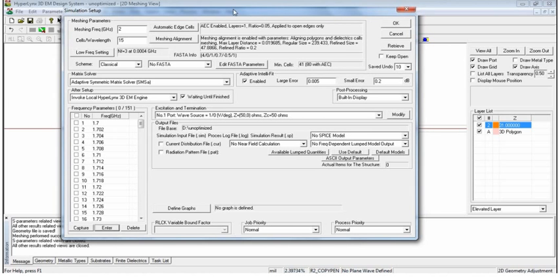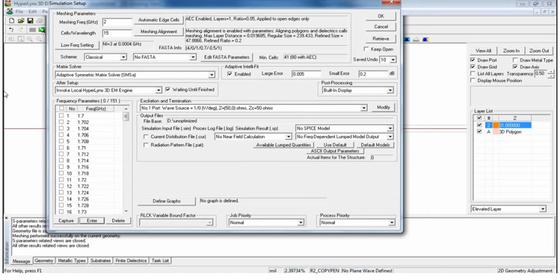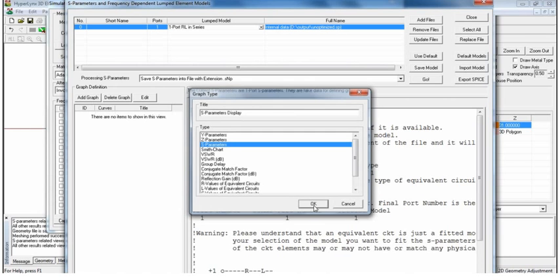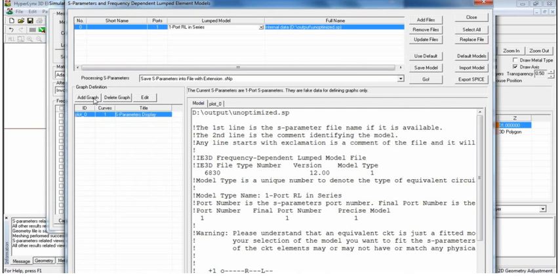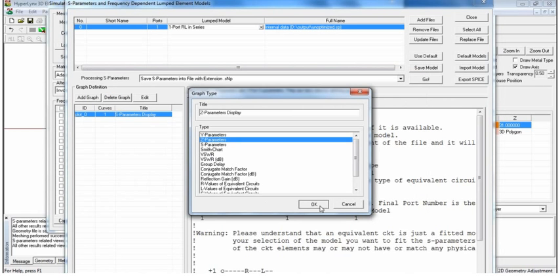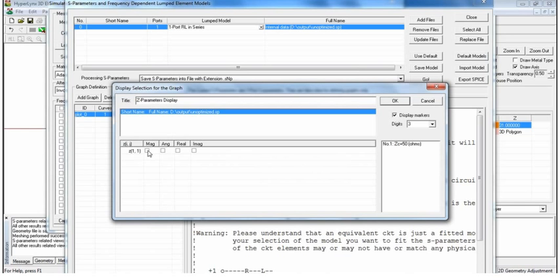again we want to define the graphs for seeing the frequency response of my antenna, or the resonance of my antenna. I need to define a graph called an S parameter chart. So there is an option for defining a graph in IE3D. So I'll just click on add graph, S parameters. Okay. Which parameter do you want to monitor? Like I want to monitor a dB parameter for it. Click on OK. Again, I need to see the Z parameter chart for it. So click on Z1. Which plot do you want, imaginary, real? So I want a magnitude plot for it.